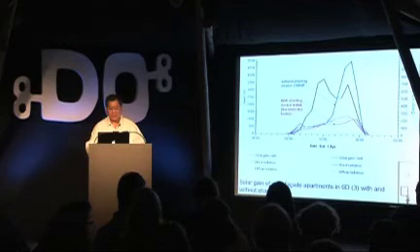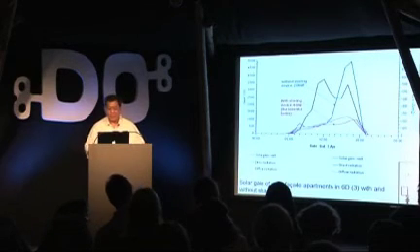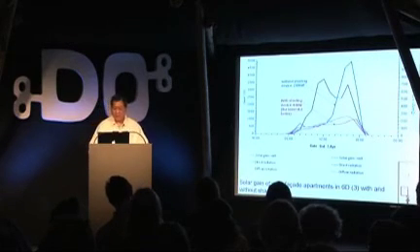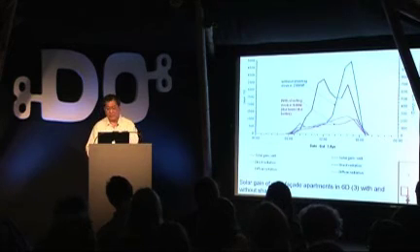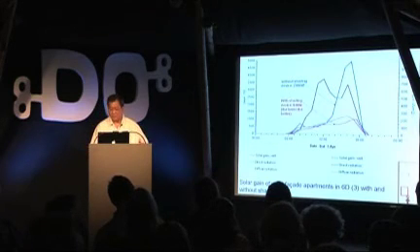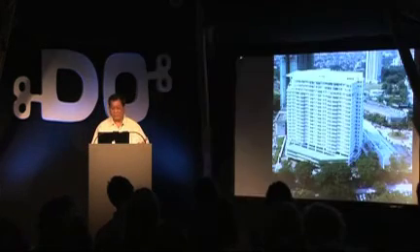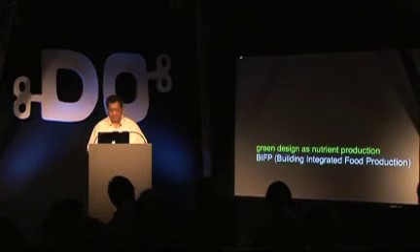And the blue graph shows that without sun shading, it gets incredibly hot. It shoots all the way up around 4 to 5. But with the sun shading, you can see the red graph. So this shows the sun shading actually works as a passive device to reduce the need to cool the building.